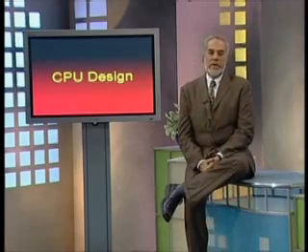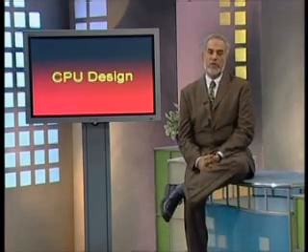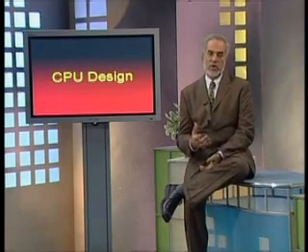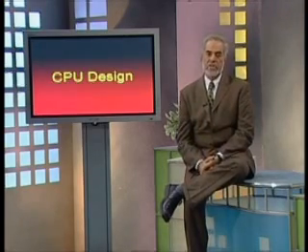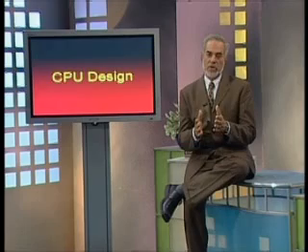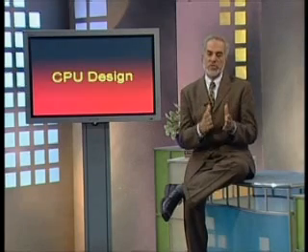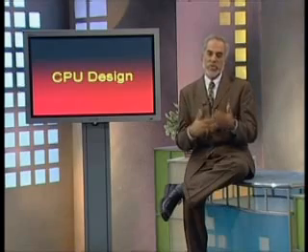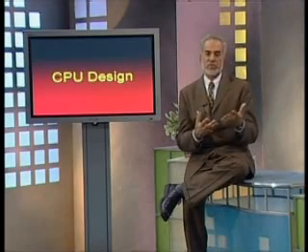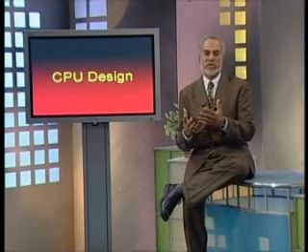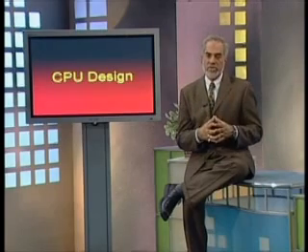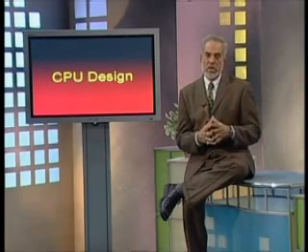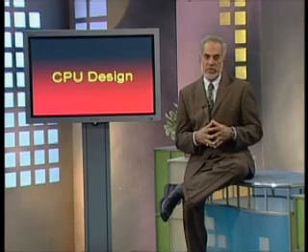In order to have synchronization from the main clock, from the master clock, we need to generate individual clocks or the steps corresponding to different timing sequences. So a sequence of timing, which we just could call T0 to T8, for example, could be generated using a counter or through a microcode.